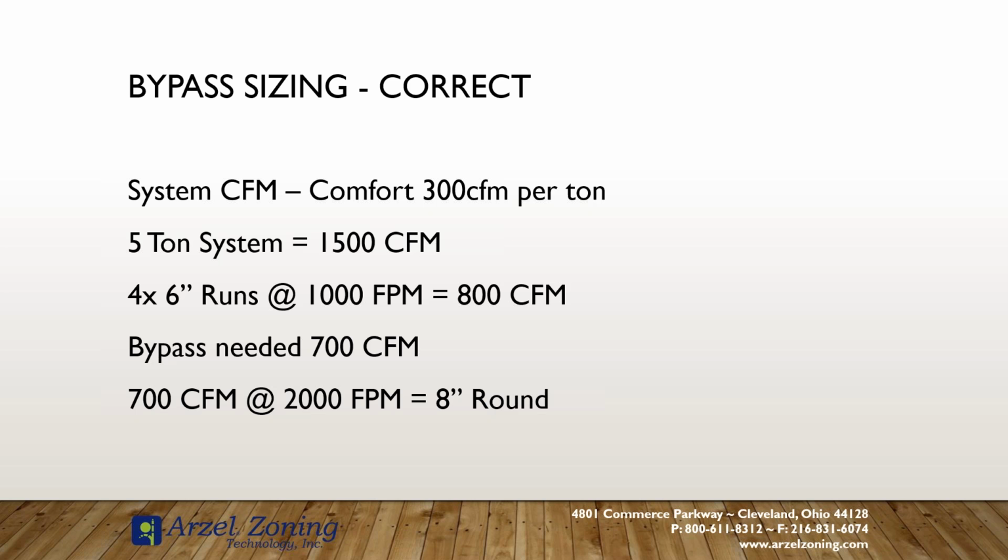Great classes. We've worked very closely with them in the past, and they helped us learn how to appropriately size the bypass. What we came away with is that when we're designing our bypass, we want to maintain maximum comfort. If we pay attention to our blower profiles, a comfort profile moves air at about 350 CFM per ton. We also know that we're not going to risk freezing an evaporator coil until we start dropping below 240 CFM per ton.